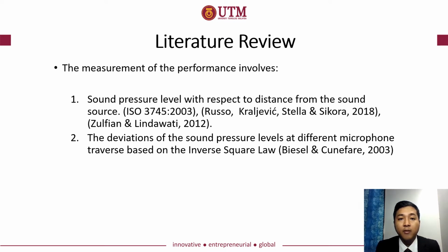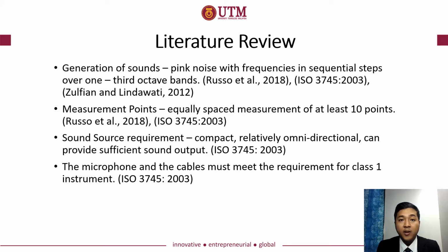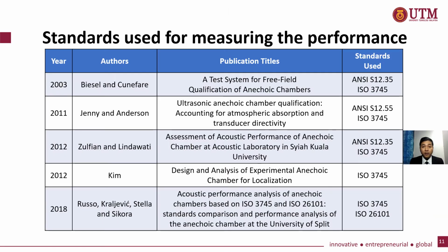Here is the measurement of performance, which involves sound pressure level with respect to distance, and the deviation at different microphone traverse. Then, this slide shows the requirement to measure the performance in terms of the sound generated, the measurement point and distance, the sound source criteria, and the microphone must meet its requirement. So, most of the research that I have studied use this type of standard. For this project, I choose the standard of ISO 3745.